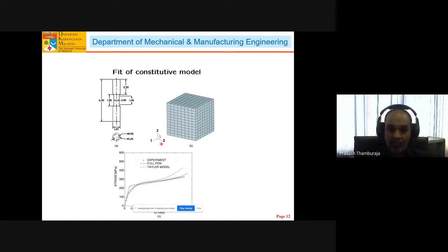So then we perform the polycrystalline experiment. This is the stress strain curve. You can clearly see some elastic deformation here, and then some elastic plastic deformation, and as you keep on going, it keeps going up. The reason you get a hardening response is that when the twinning response is completed, you get elastic deformation again. This indicates that some grains have already completed the twinning process, but some are still twinning. So it's the competition between the elastic and elastic plastic deformation that is causing the hardening response.